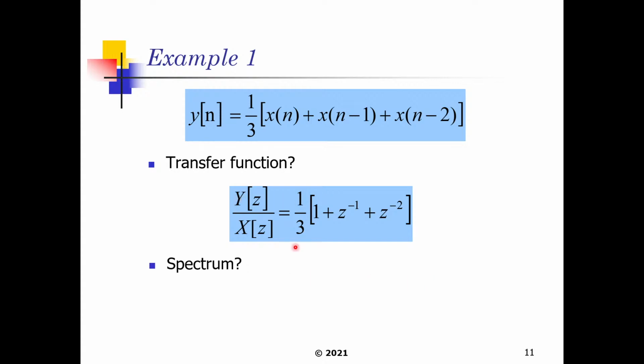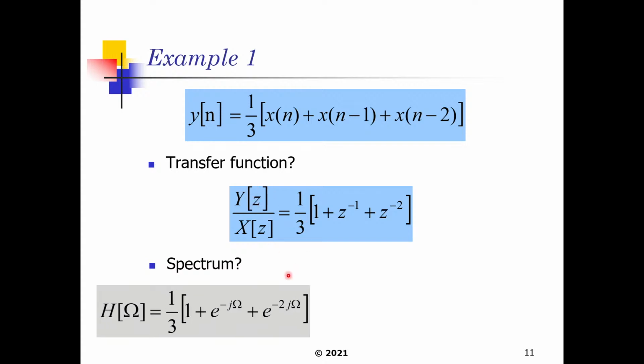So to get the spectrum of this, because this is in terms of z, we need to transform this such that instead of Y(z) and X(z), which is basically H(z), it becomes H of capital omega, where each one of these z's here is just going to be e to the j omega in particular. This here is basically the same thing as a summation series.